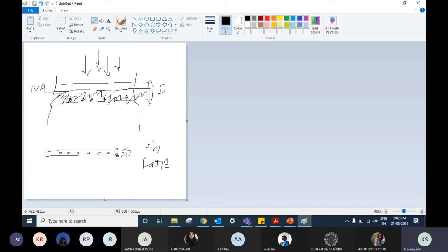So in order to address the deflection, in order to address the fire rating, in order to reduce the concrete so that it can be put somewhere where it is better utilized, the idea was to go for a waffle system. Now they have uniaxial bending slabs, which bend in one direction, and there are biaxial bending slabs. Research is still going on, and people are trying to use some pre-stressing strands in addition to the waffle slab to enhance the slab system.